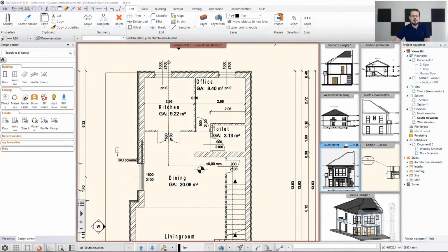It might happen that your building project consists of elements which should be demolished, and you want to show multiple instances of the same floor plan with things which would be demolished and built later on. Of course, you can go around and select elements and delete them, but that would be a destructive way of modeling, and you would have no original plan to refer back to. Luckily, in our software there's a tool for this kind of change tracking, and that is called Phases. It's under the Edit menu, by the way.